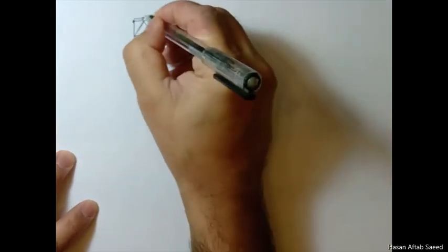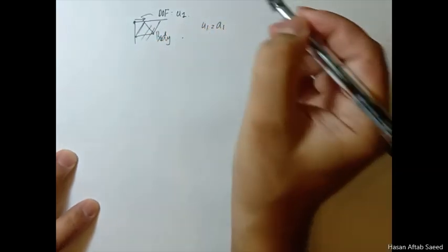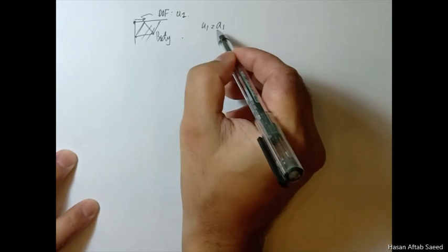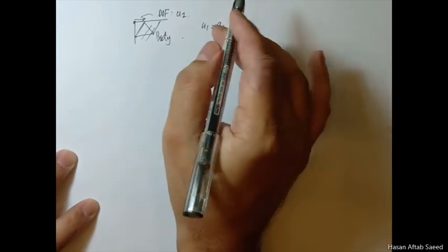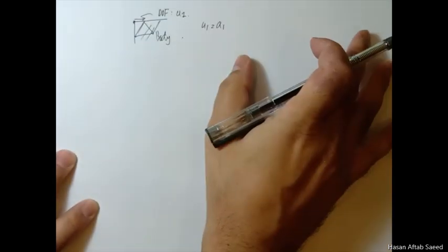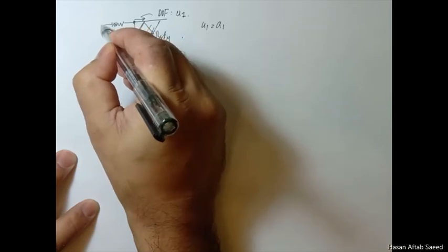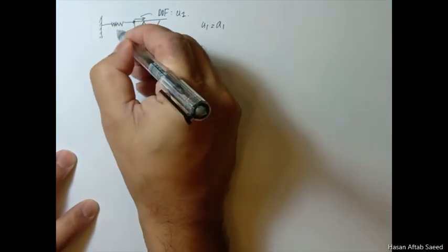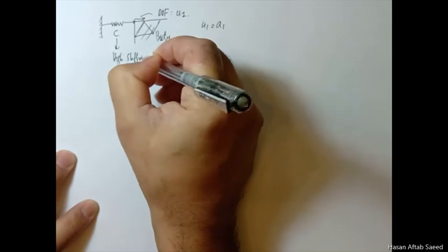Let's call this degree of freedom u1. This is the u1 degree of freedom, and you want to apply a1. a1 is a constant, a number, for example 2 millimeter, 5 millimeter, whatever that is, it's a number. So where we depart from the traditional methods is, instead of applying u1 is equal to a1 on this node, like I mentioned earlier, I'm going to use a spring with a stiffness C, high stiffness.